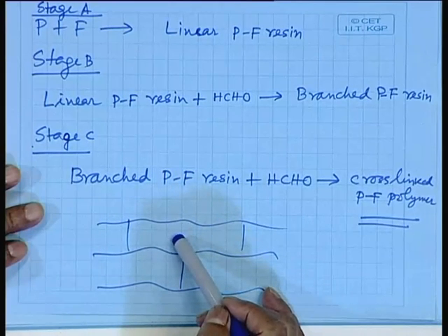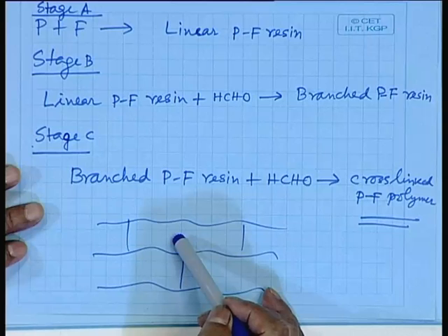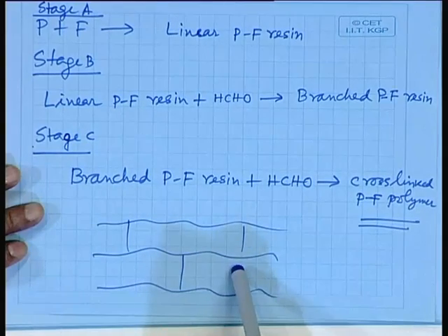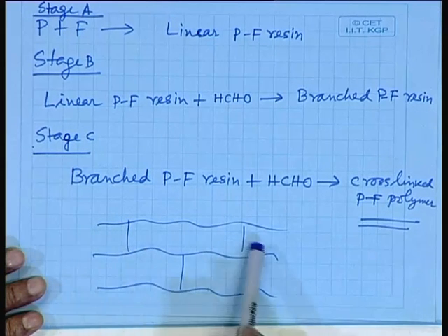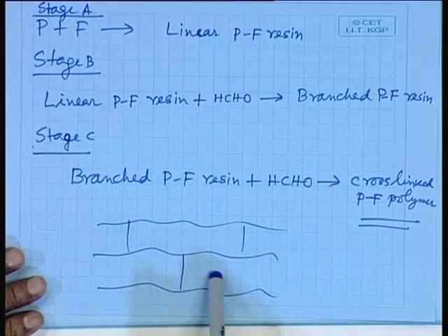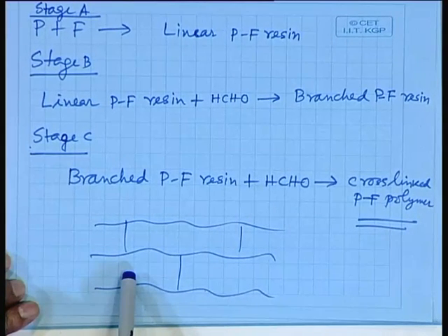These thermoset polymers are infusible by heating; they cannot be fused or melted by heating, and they are also insoluble in any solvents because of a three-dimensional network of polymer molecules. They form a three-dimensional network of polymer chains. That is why these polymers are insoluble and infusible, because in order to make them fusible, meltable or soluble, these intermolecular bonds have to be broken, whereas thermoplastic polymers are linear molecules.